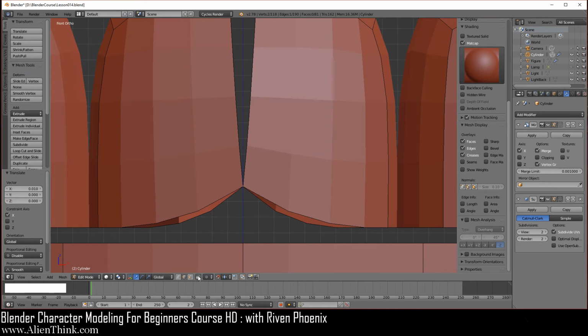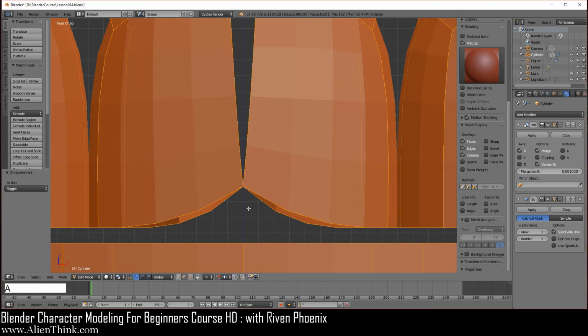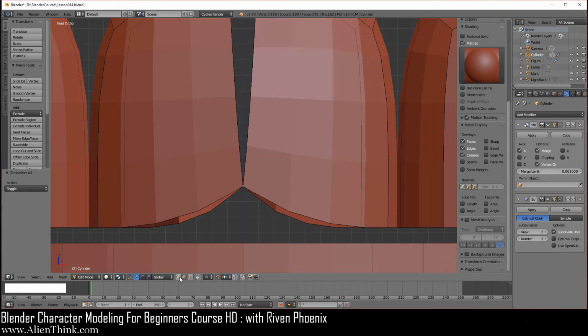Now we're going to make sure that this thing is on, okay? So you can see the vertices in the back. You're going to do A to select everything, A to deselect everything, click on the vertex select mode, press the C key, and then click over here, right click to get out of it.